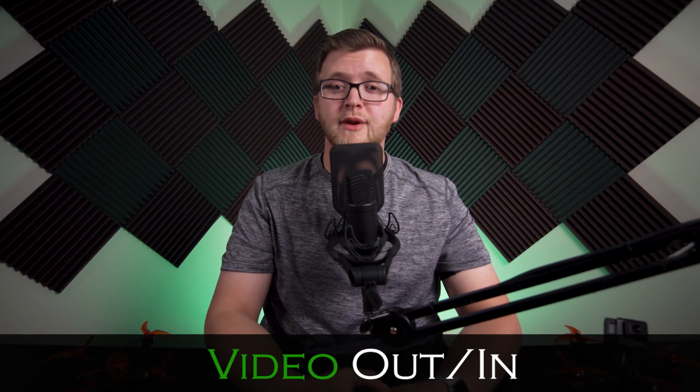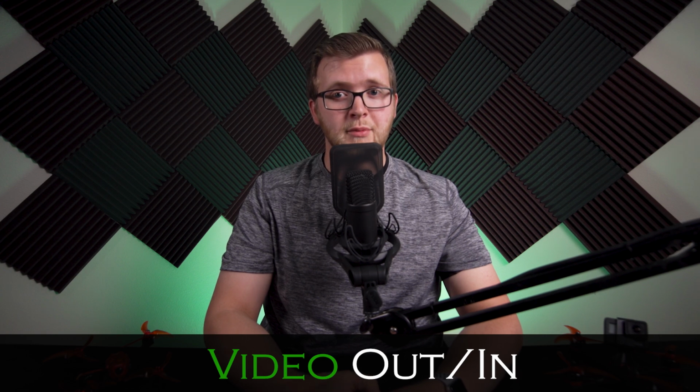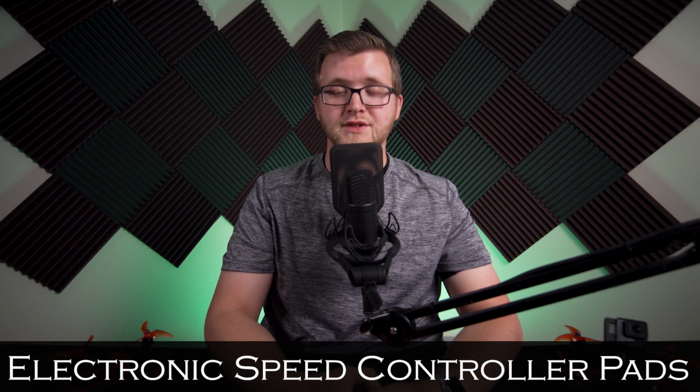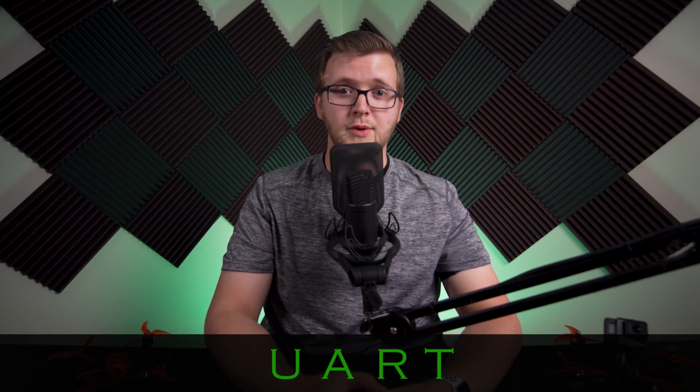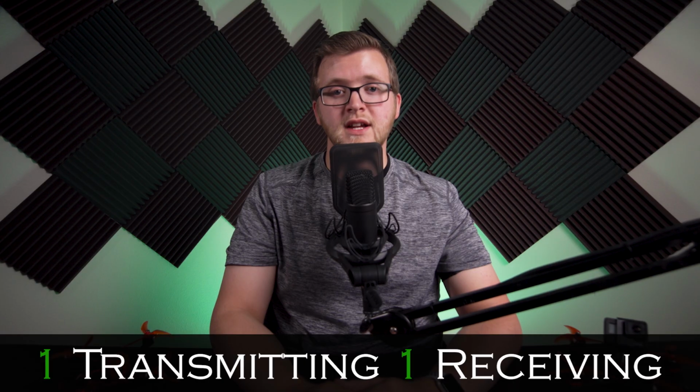Most flight controllers will have at least the following connections: video out for a video transmitter, video in for the camera, electronic speed controller signal pads for each motor, and universal asynchronous receiver transmitters, or UARTs for short. For our purposes, UARTs are one transmitting and one receiving signal connection. It is important to understand UARTs because you will need to make sure there are enough for your purposes.